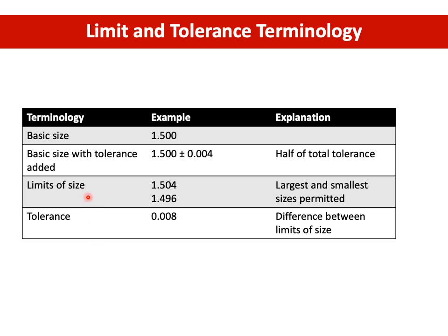The limit size is the way you put your dimension, where you put your limit dimensions with the larger size on top and the smaller size on the bottom. So the limit size is between these two values.